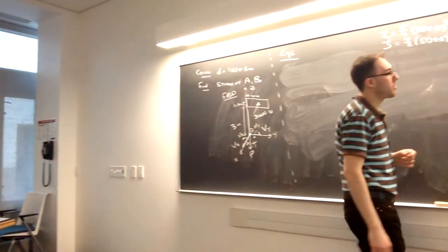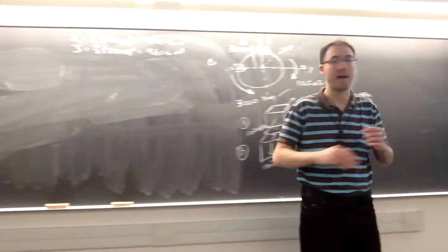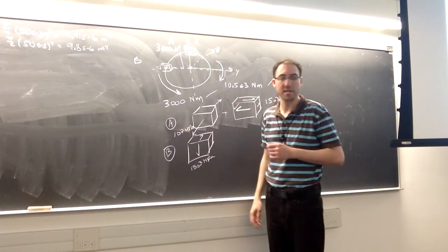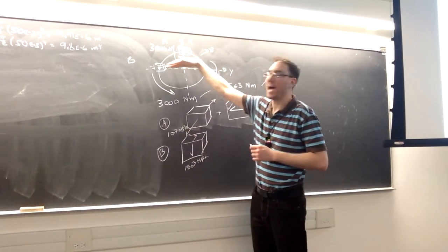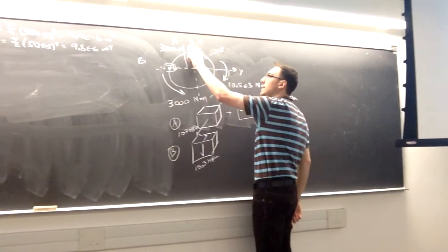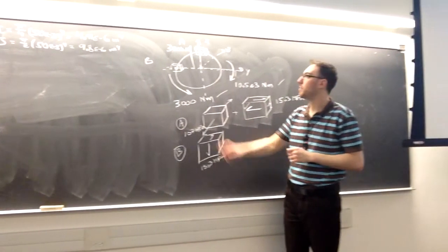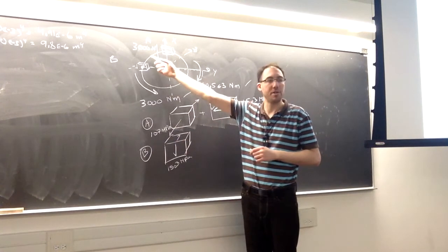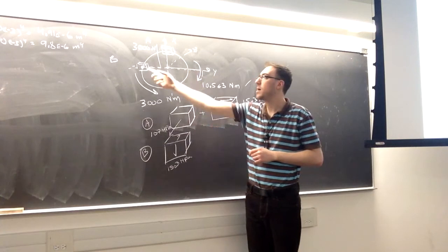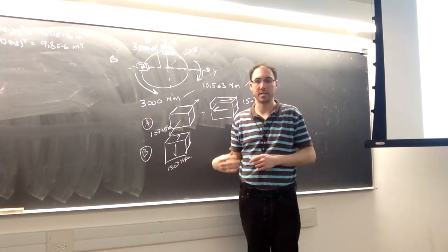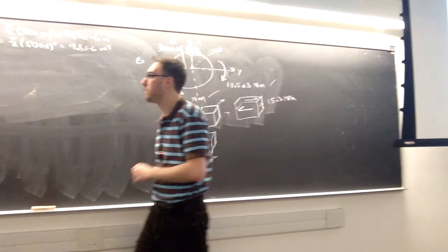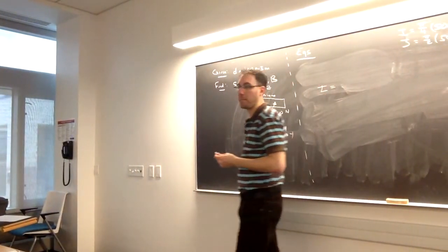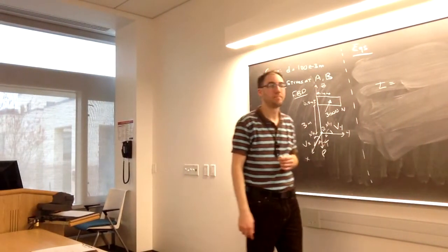Right, A will be 0 because for transverse shear, it's going to be 0 at the top and the bottom of the cross section. So with respect to that horizontal neutral axis, A is at the top. So the Q value will be 0 for point A. So there's no shear stress from the 3,000 newtons at A, but at B, because it's on that neutral axis, it will actually be at its maximum value. So we only have to calculate the transverse shear stress at point B, since A will be 0.